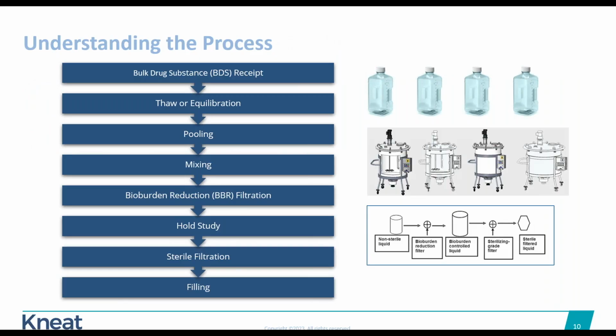All right, so as you can see here, there's another box here that was not there before for the hold study. So again, this is just an example. This hold study can be earlier in the process or later in the process after filling. But for now, I'm going to put it between the two different types of filtration. Typically filling is a common area where there's lots of delays during the process. So a lot of the times I would see clients have a hold study as close to filling as possible.